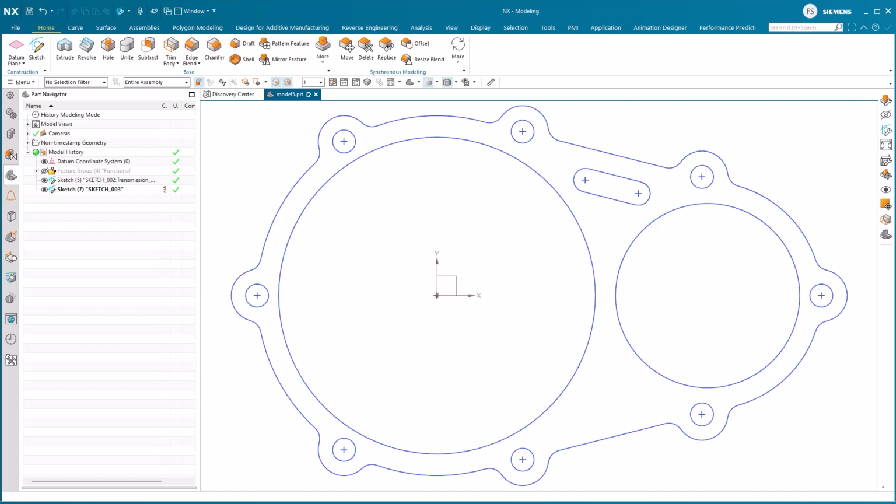You have seen that the sketch checker produces issues that are represented as visual tags in the graphical screen, as well as issues in the issues column of the sketch navigator. You have seen that the issues can be addressed by either using the correct option with the suggested solution, ignore the issue, or deactivate the specific check from further use by the sketch checker. You have seen that the ignored or deactivated issues can be turned back on under the settings option.